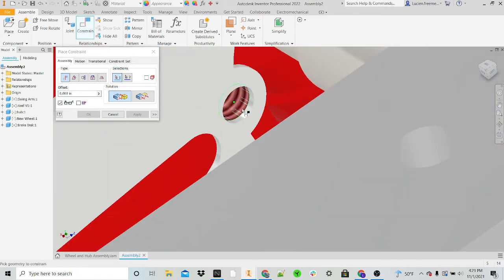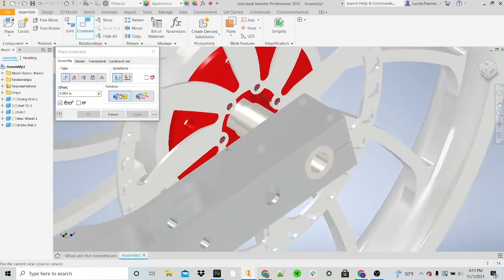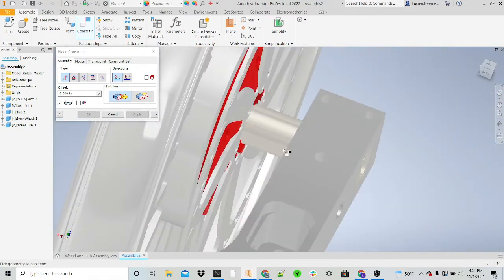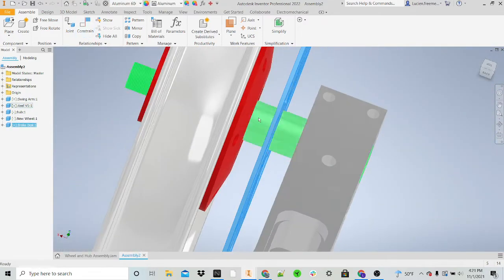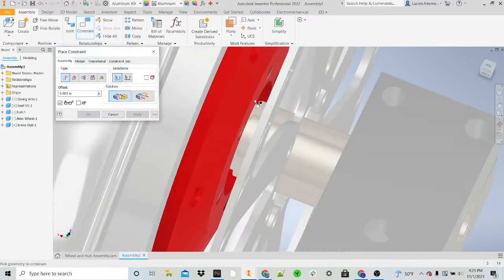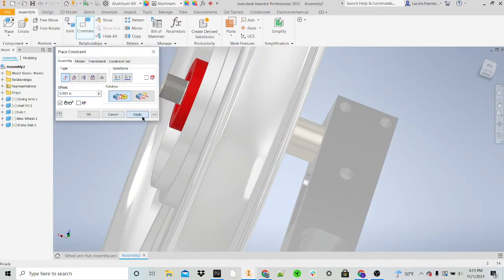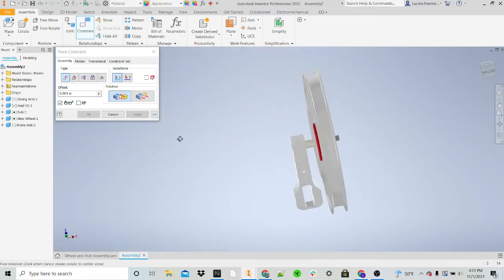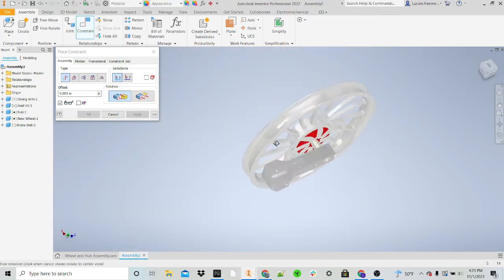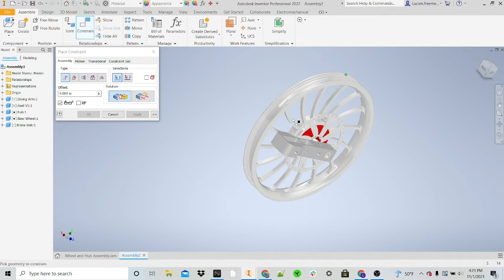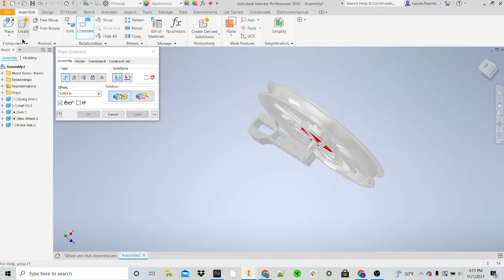So we'll take, come on, that one. Perfect. And then we can just take surface to surface, and then we should be there. So we'll go constrain, surface, surface. Done. And there's our brake caliper. It's on our wheel. And so the entire wheel portion is finished, unless you want to put a tire on this, which we haven't done yet.